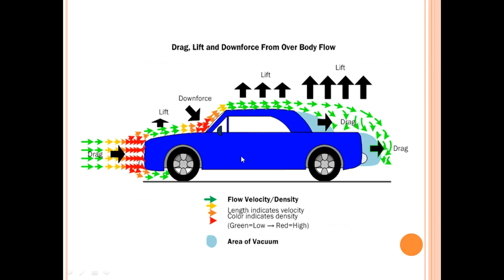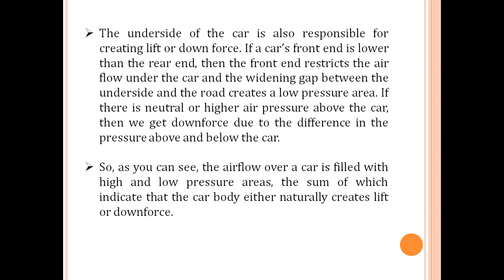So the underside of the car is also responsible for creating lift or downforce. If a car's front end is lower than the rear end, then the front end restricts the airflow under the car, and widening the gap between the underside and the road creates a low pressure area.